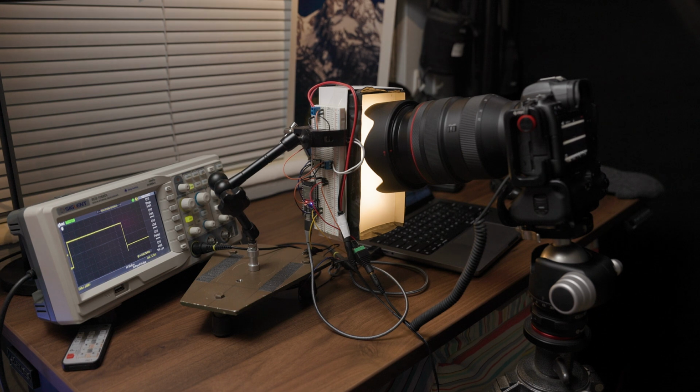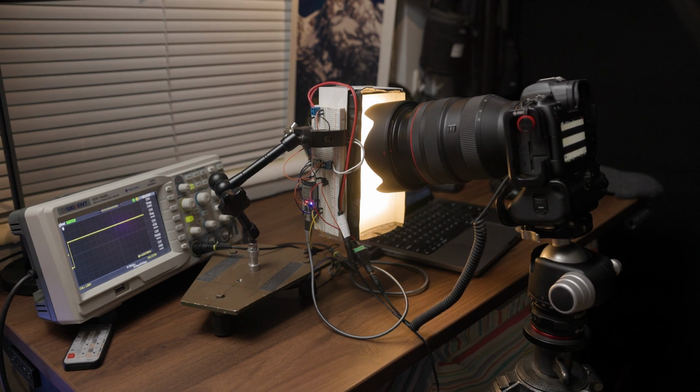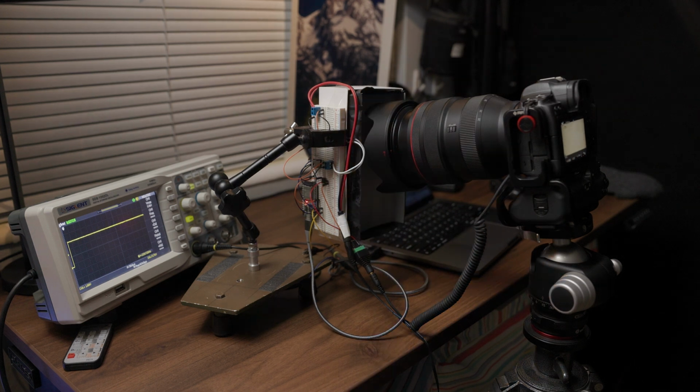Now, the pulse times that I chose here were chosen largely to be a range that covered the fact that my shutter speeds would either be a 4,000th of a second, which is 250 microseconds, or a 2,000th of a second, which is 500 microseconds. So I have a pulse time that's a quarter of each of those and 4 times each of those settings. I then pull the files off the card, run the files through the post-processing software, take this text file, stick it into Excel, and then average together the various pulse time tests for each of the camera settings that I'm investigating.